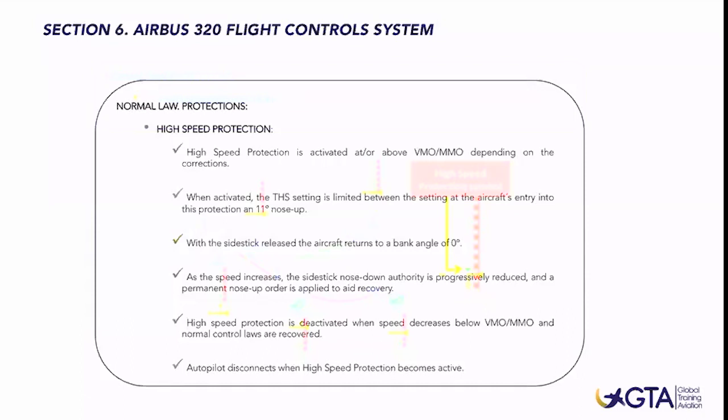If our indicated airspeed is still increasing and entering the red strip bar, the next thing that will happen is that as soon as we reach the green dashes indication, we'll get the ding, ding, ding aural warning and the master warning red light, which means that we have exceeded this speed limit.